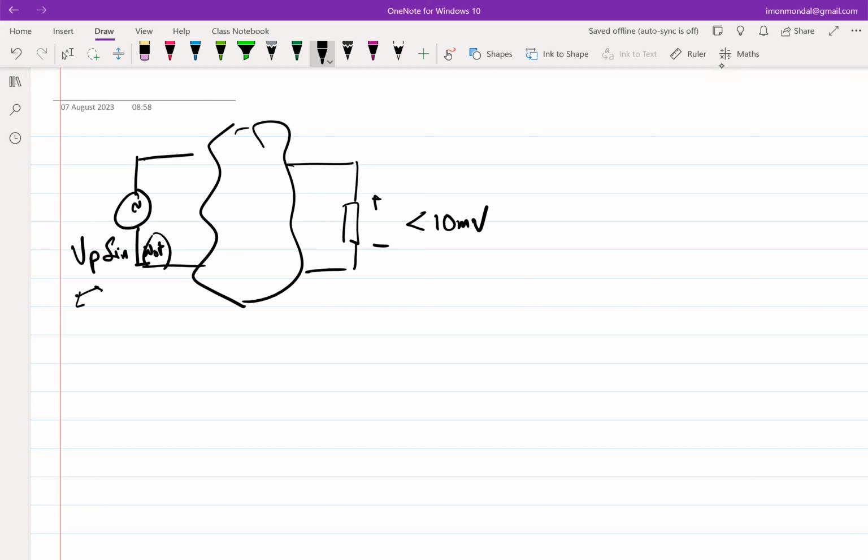but it depends on how the nonlinear device is connected to the rest of the network. So the job of the designer is, let's say I have a requirement that Vp is quite large, say 1 volt, but I have to use a device which can only tolerate a voltage swing of 10 millivolt. The job of the designer will be to build the network so that I can handle the 1 volt swing at the input while respecting the fact that the nonlinear device doesn't see more than 10 millivolt of swing. This type of configuration you will see later in the course, but for now this is something you should keep in mind.